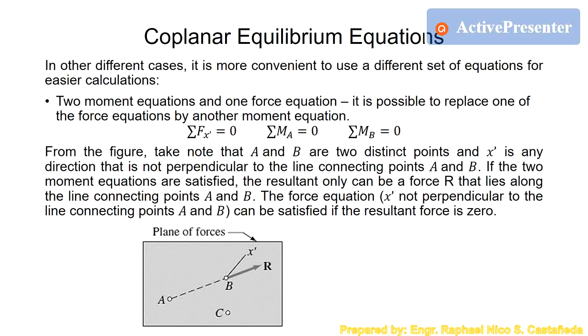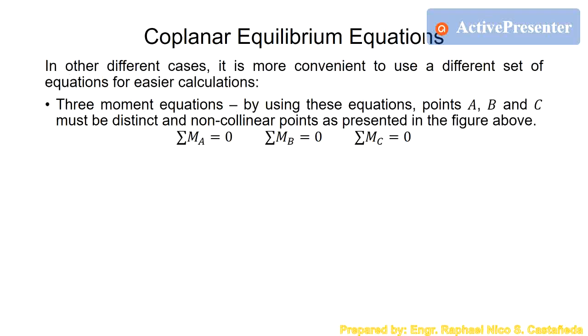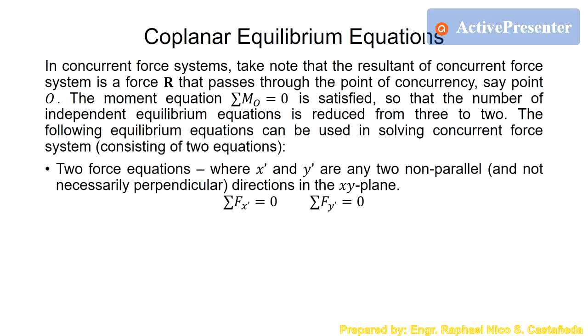Next, we can have two moment equations and one force equation. So it is possible to replace one force equation with another moment equation. The other one is the three moment equations. You can use three moment equations, replacing the two force equations with two other moment equations. So these are the possible equations you can use.